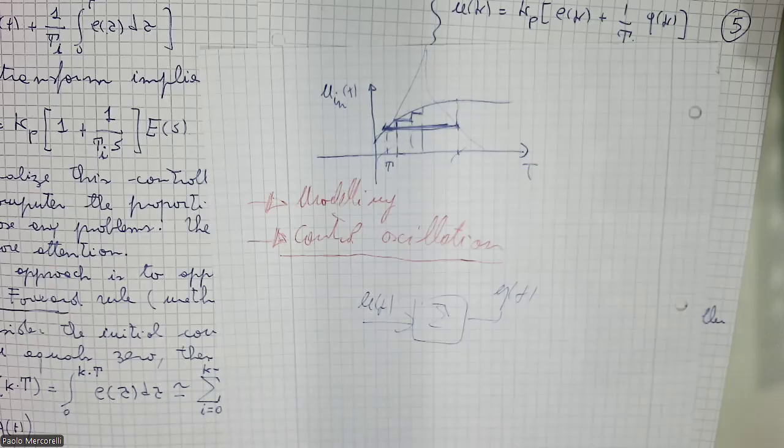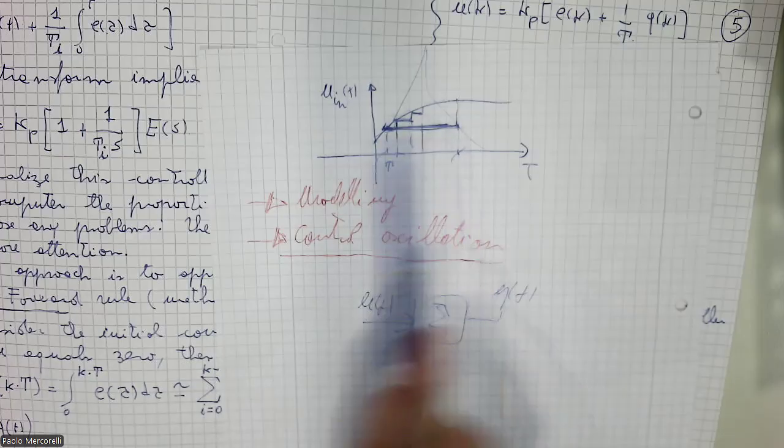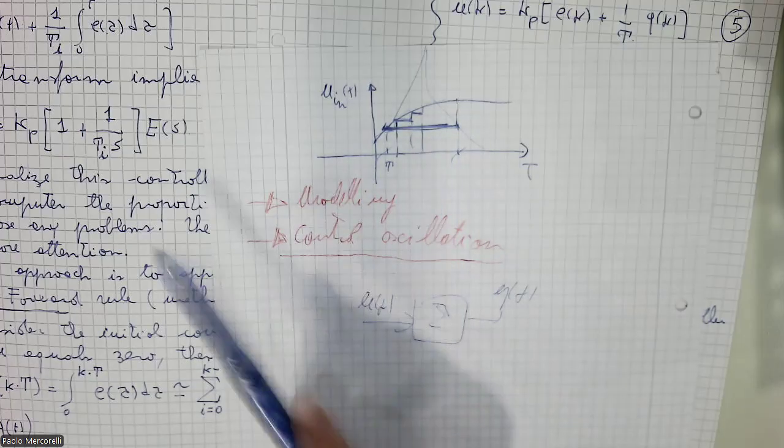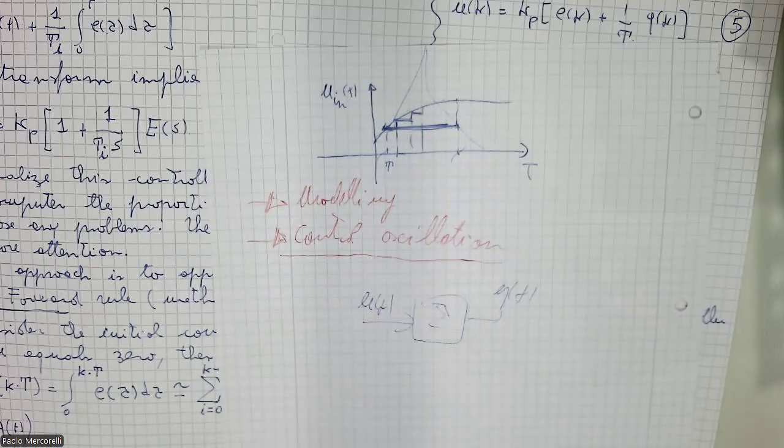In this case, we don't have this kind of problem. The operational amplifier controller is the best. But the problem is drift. I don't know if there is a new generation of operational amplifiers which avoids this drift, where they change the characteristic because of the temperature or something like that. I'm not an expert, but the digital controller, the discrete controller, is really worse.